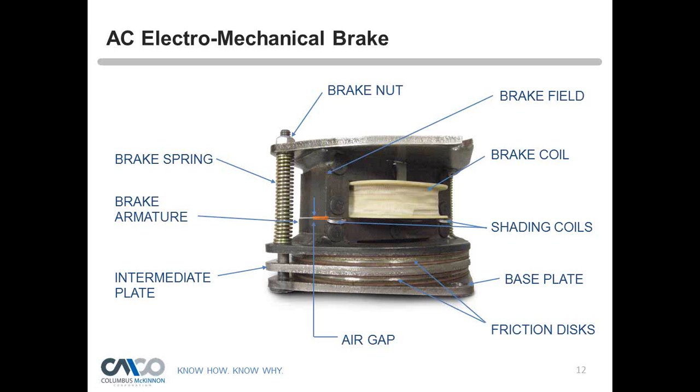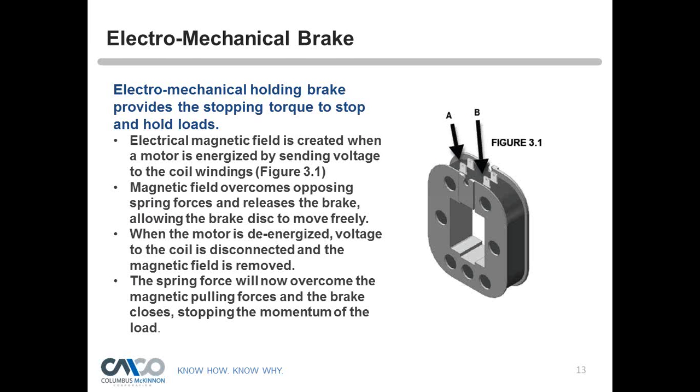And basically what we do is we have a coil that is the wires wrapped around a core, and that gets magnetized, and that basically will pull that gap shut and allow that very fine gap right here to transfer between all the friction plates and allow the motor and the gear train to spin, which allows the hoisting action in either up or down position.